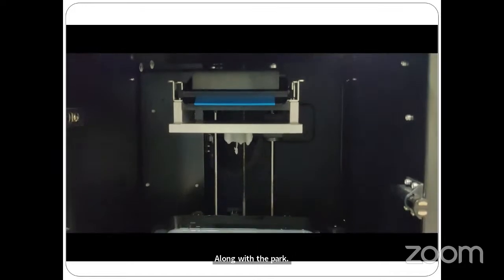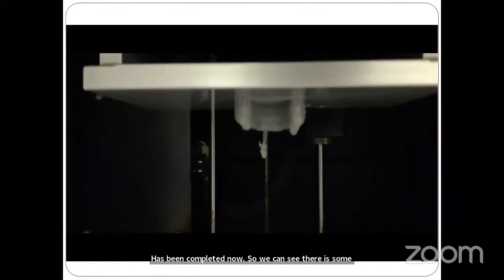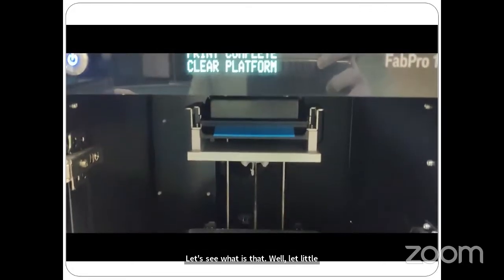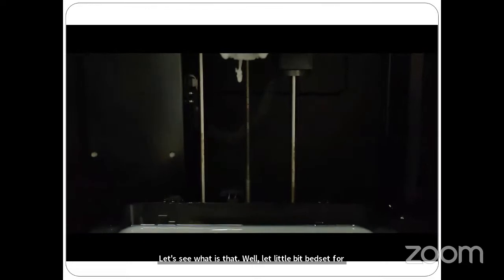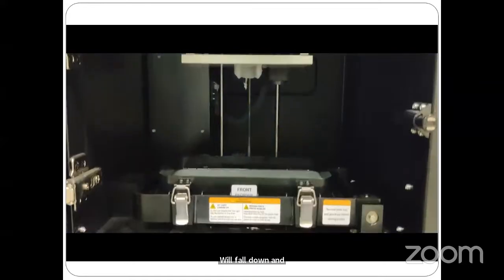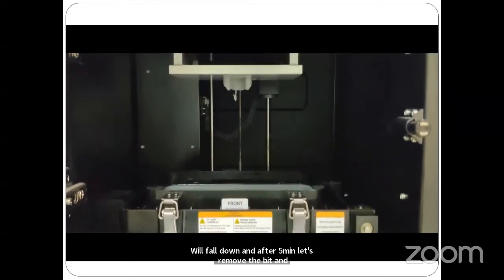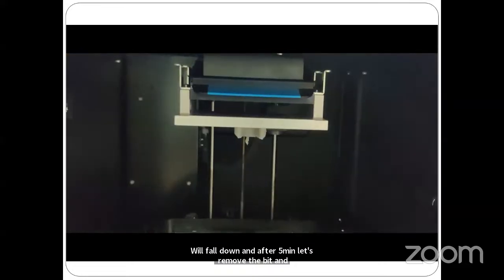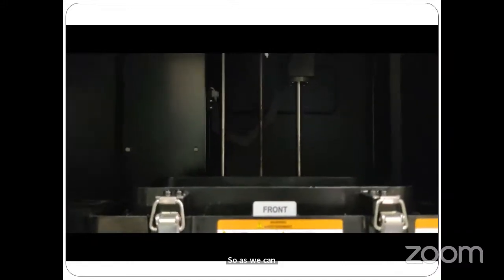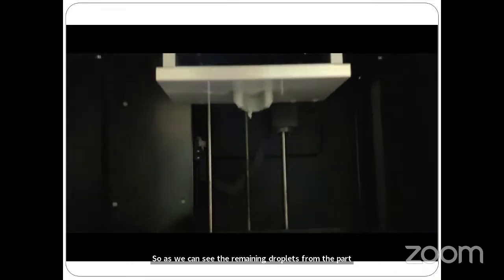The part has been completed now. We can see there is some additional cured component with the part that we don't want. Let's see what that is. Let the bed sit for 5 minutes so that all the remaining droplets of the resin will fall down, and after 5 minutes let's remove the bed and check whether we have got our part or not. As we can see, the remaining droplets from the part have fallen down. So now we can remove the part.